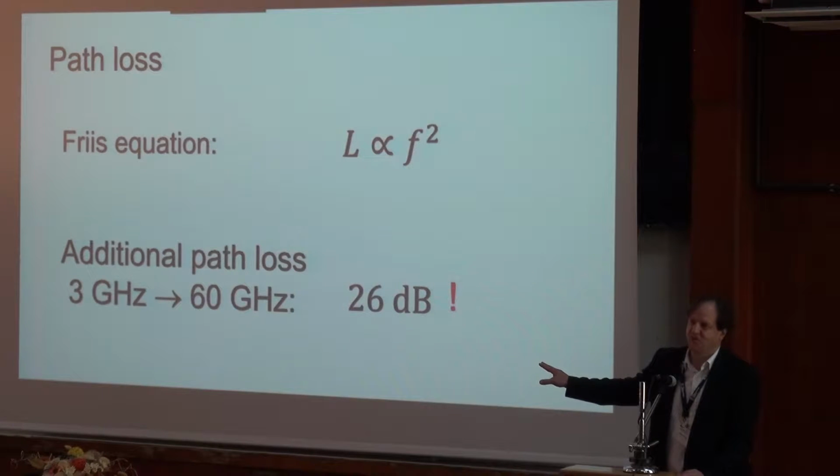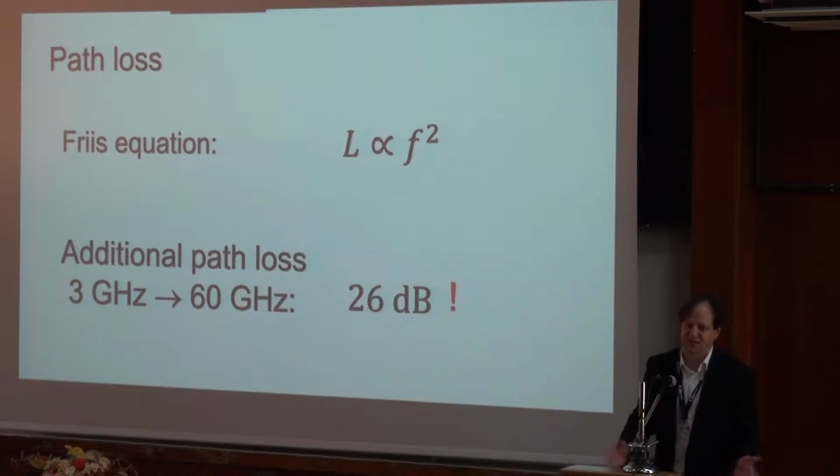And that imposes a number of challenges, because imagine you have a receiver in your mobile phone, you have an antenna array in your mobile phone, you need to form your beam to where the transmitter is, the base station, and then you need adaptive beam steering. You need phase shifters at the receiver, at the RF front end, and those are very expensive and energy inefficient components.